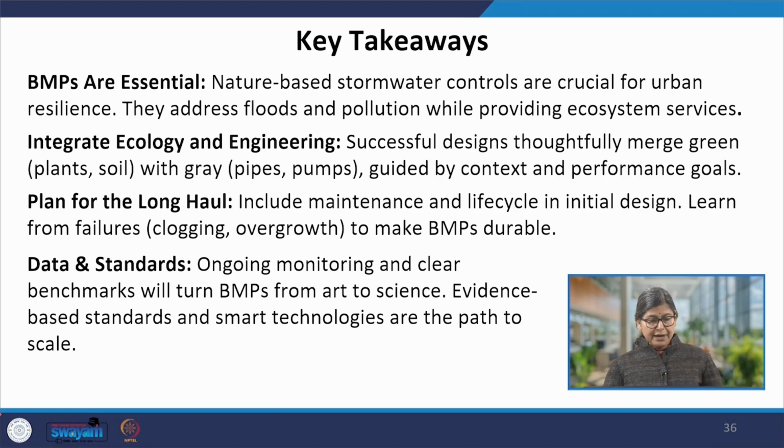Integrate ecology and engineering. Successful designs thoughtfully merge green plants and soil with grey pipes and pumps, guided by context and performance goals. Plan for the long haul: include maintenance and life cycle in the initial design. Learn from failures, clogging, overgrowth, etc., to make BMPs durable. Data and standards: ongoing monitoring and clear benchmarks will turn BMPs from art to science. Evidence-based standards and smart technologies are the path to scale.